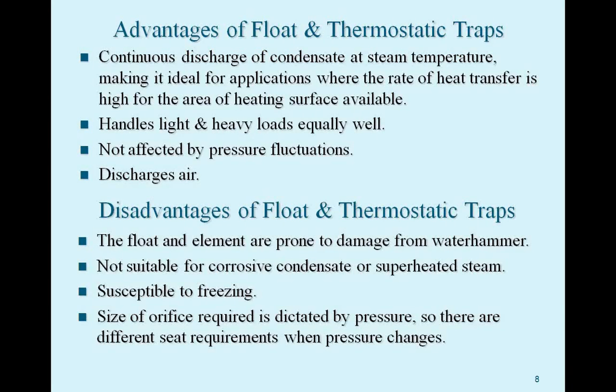Some advantages: they continuously discharge. I mentioned that they are modulating, so they're good for applications where the rate of heat transfer is high. You see these on a lot of heat exchangers, for example. They handle both light and heavy loads very well, so they will adjust to varying condensate loads. Pressure fluctuations don't really hurt them, and they do discharge air.